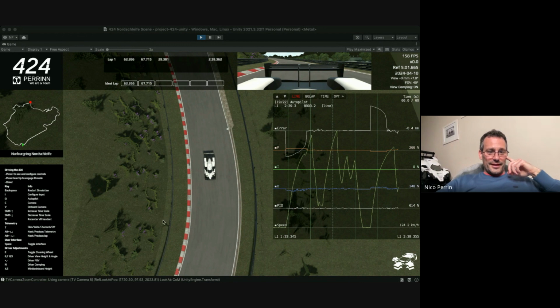Okay, and I've got another question from Yash. When I explained understeer and oversteer with respect to the difference between the slip angles of the front and rear, does that also account for the understeer and oversteer induced by the power difference? Yes, it does. Exactly. The understeer that you see from the slip angle at the end is more or less the result of everything. If you start playing with aerodynamic balance, power distribution, and the car snaps and oversteers, you will see it in the slip angle.